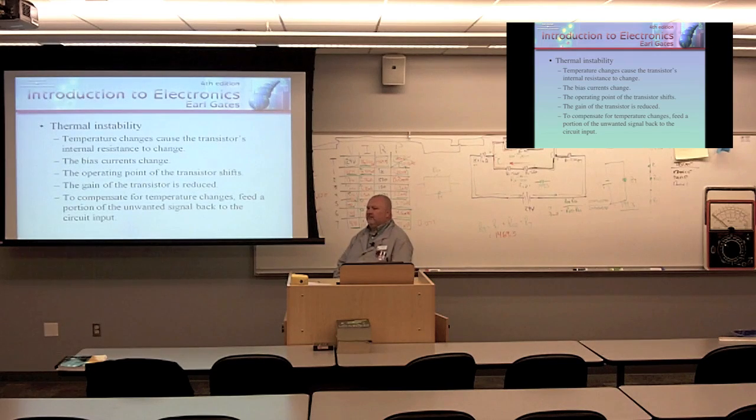Thermal instability, of course, is a big problem with the utilization of semiconductors in general. Temperature changes cause the transistor's internal resistance to change. The bias currents then change. The operating point of the transistor shifts. Operating point means how much it's amplifying.